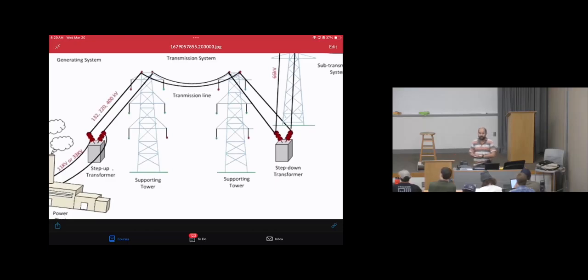Then, when we transmit the power, why do we need to add a neutral? We don't need it. We can remove the neutral wire and transmit the power for high voltages or extra high voltages or even medium voltages as only A, B, C without a neutral. And that's what's happening in real life. We can save more money by avoiding using the neutral, because transmitting the power from A to B without any disconnection for 100 miles, 200 miles, I can save more money by removing one conductor. That's one advantage, right?